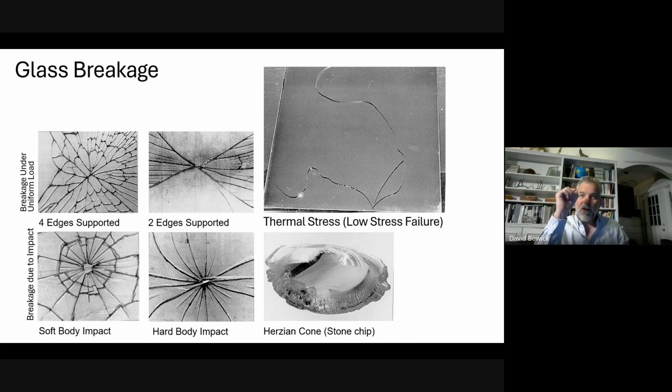Somewhere on the perimeter, you're going to get a tiny little flaw, and there's going to be sufficient tension that a crack is going to start to propagate from that. So you have experienced these. Probably you've been in a car that has a thermal failure in the windshield, and you'll see this lazy crack just migrating around. They generally start just above the dash. Does that make sense? They start just above the dash because when you've got your heat on, you're blowing a lot of hot air up on the windshield, but the bottom might be in contact with something cold.